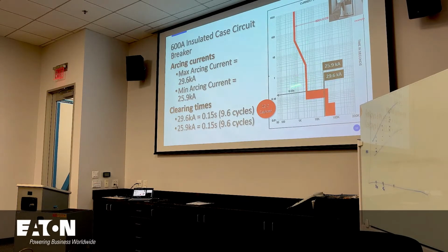So short time pickup, I can move that left and right. The only reason I would do that is for motor starting possibly, transformer inrush possibly, selective coordination, or if I want to use it for some arc flash reduction to give me this knee, take a knee, reduce incident energy, get it to a reasonable value, better than going up to this portion. So I might do that.